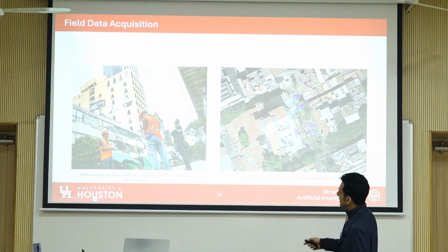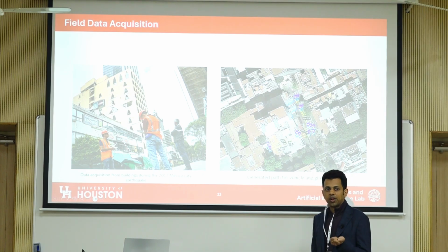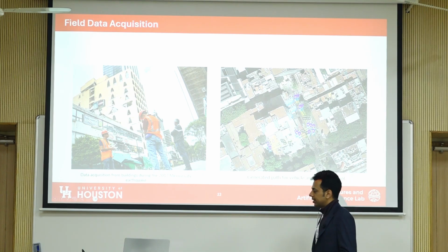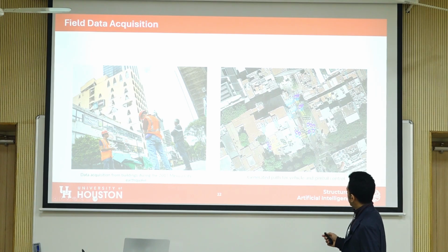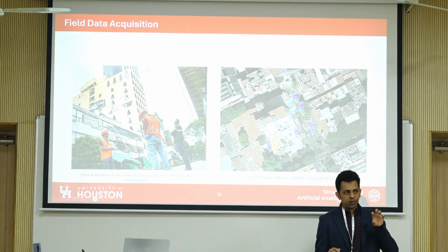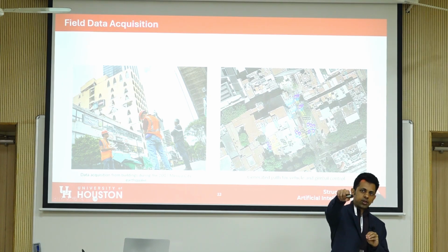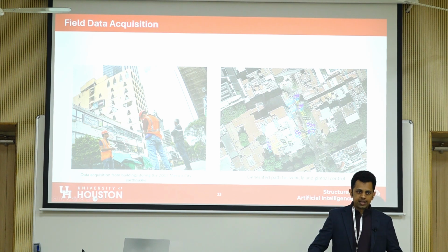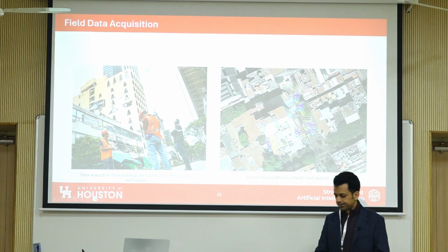But in any case, in 2017, this is the path that we chose. This was with a DJI drone, and we used a software called Litchi, which is just a $25 app you can buy on the Play Store. These balloons in purple, those are points, those are keyframes for where the drone needs to go. And for each of the points where the drone needs to go, there's a point where the drone needs to look. So the drone has a gimbal with a camera, and the gimbal controls where the camera is looking.